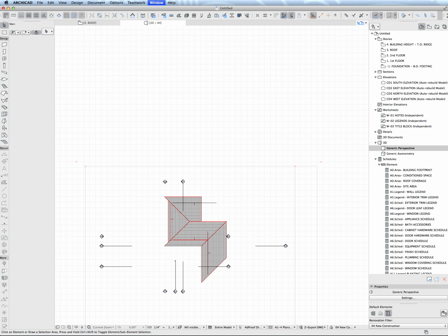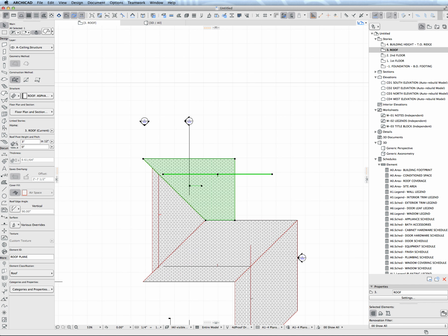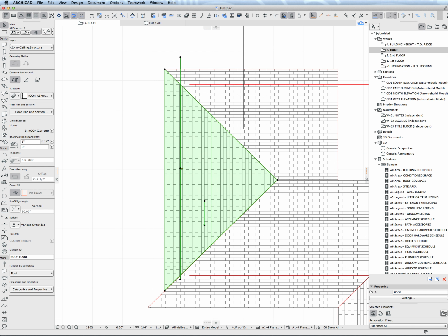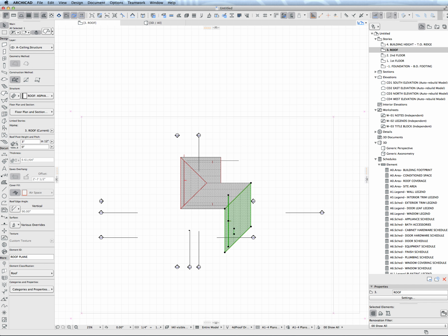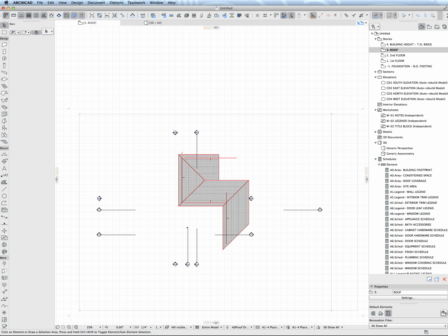That's when you're editing in 3D. If you're editing in 2D, it's always in the horizontal plane. So if I come from here and offset that out 2 feet, and come in here, and once I get one edge offset, then I can really quickly adjust the other ones to match the correct overhang. So even using single plane roofs, you can really quickly come into a pretty detailed and elaborate roof shape.